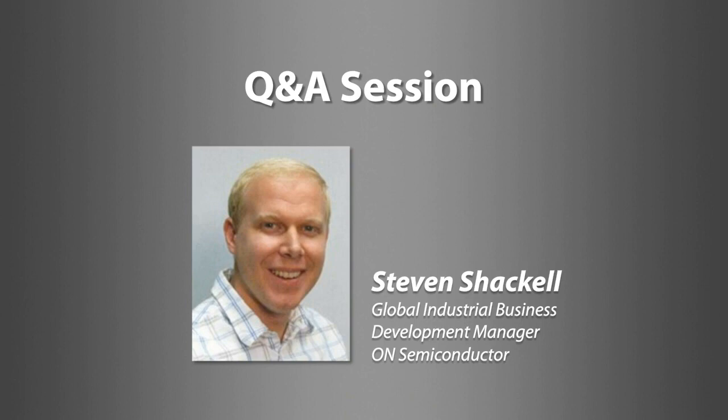In terms of new technology, I would point to gallium nitride, as we see a need for gallium nitride in the 100, 150 volt space. So I would point you to looking at gallium nitride for low voltage applications if you're looking for the next generation silicon or semiconductor technology.